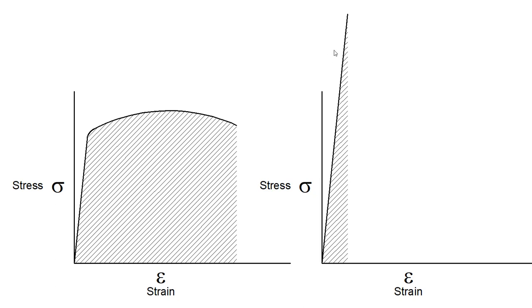I will say one last thing about this little side trail we're going down, is that the modulus of elasticity for this particular steel is going to be the same. So this is going to be unchanged through the heat treating process. They'll have the same slope here, but what we're doing is moving this yield point up and changing the amount of plastic deformation that's available.